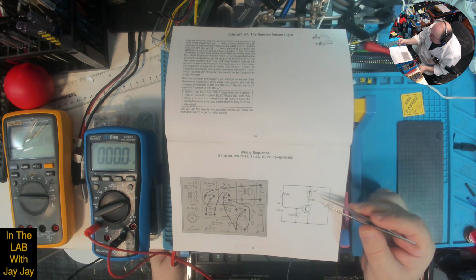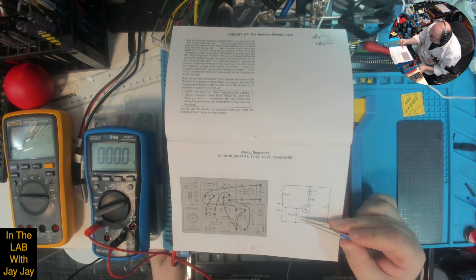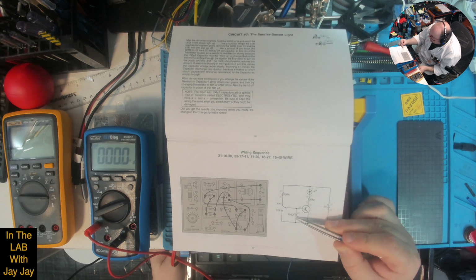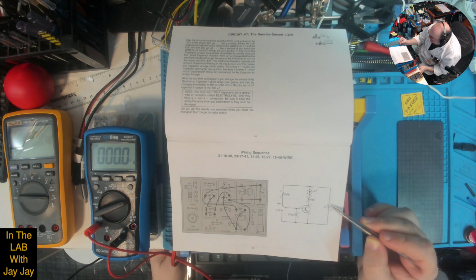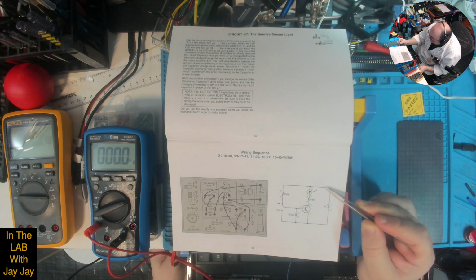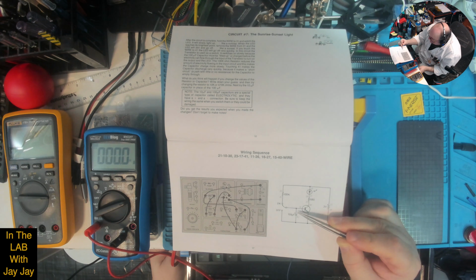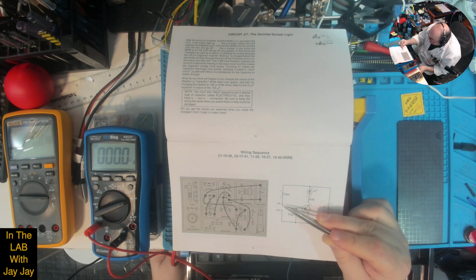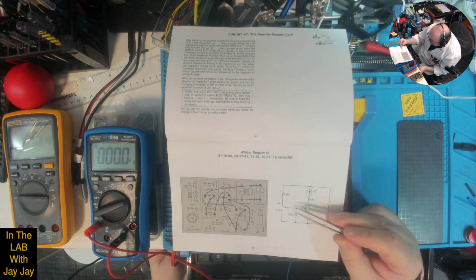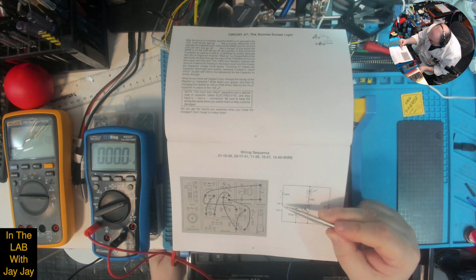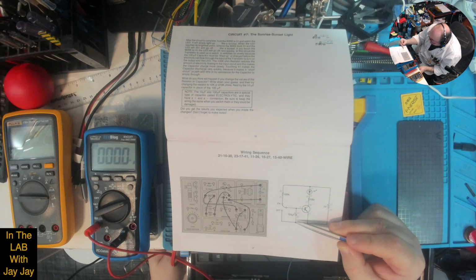It's not being powered by the capacitor. The LED is being powered by the battery. And the capacitor is affecting the current that will flow through the base of the NPN transistor. So what happens when we turn it on through this capacitor, through this 100K resistor, the capacitor begins to charge.